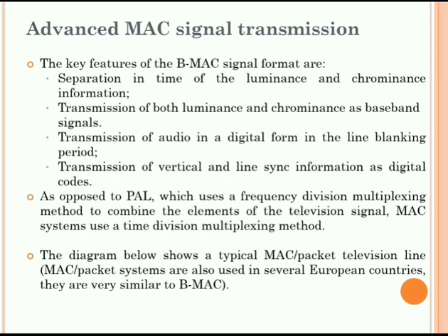Though there are these technical challenges, the MAC signal has many advantages. The MAC signal can offer higher performance than the composite system because of separation of luma and chroma signals. We are separating these two signals, which eliminates the cross modulation, and use of the full bandwidth of luma and chroma signals is possible here. In MAC, the picture synchronization is ensured by means of the time multiplexed data signal. With the MAC signal, higher performance is readily possible because of separate components.